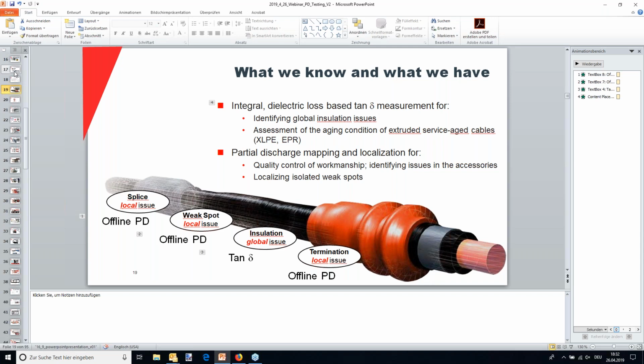For a service-aged cable, you test up to 1.7, and a very common threshold for people to take action and be very concerned is 1,000 picocoulomb in the splices, for instance. We have utilities that are way stricter, and utilities that are a little more lenient. But on average, as a company, you have to come up with your own plan on how often to test, what the thresholds are, and what actions to take.